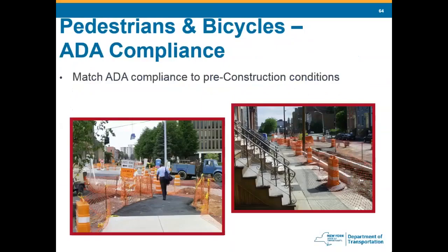ADA compliance, I think Tom probably talked about this earlier. Again, we don't need to create a sidewalk where there wasn't one before, but if there was one and we've taken it out, we need to accommodate them somehow, right here. ADA compliance to pre-construction conditions. So we need to give them something. If they had a sidewalk before, we need to give them something to walk on again.